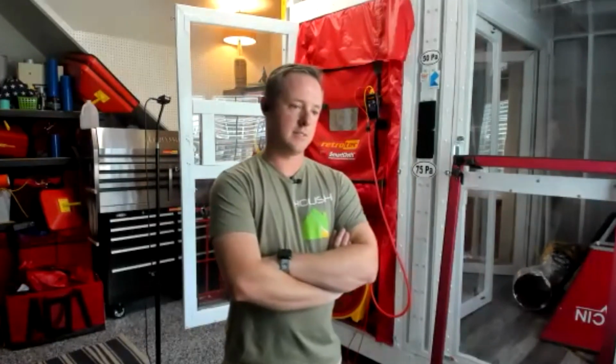There's someone asking about roughly how much square footage or volume a single fan could cover. I just commented a quick check: you can do your total volume times your air change rate and then divide that by 60, and it'll tell you the CFM that you need. Do you know of a recommended square footage per fan? Yeah, you really can't look at it like that.